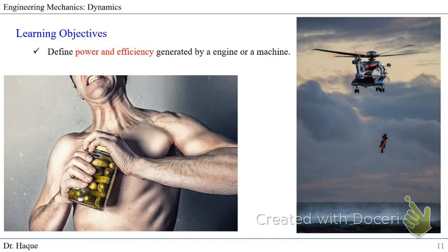Is it 1 meter per 30 seconds? What would be the acceleration, and what is the efficiency of the motor I'm buying? The power you put into the machine is not always at 100% efficiency, so you have to consider that and then make your decision.